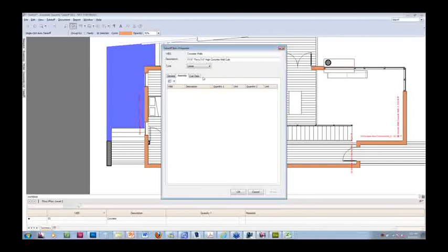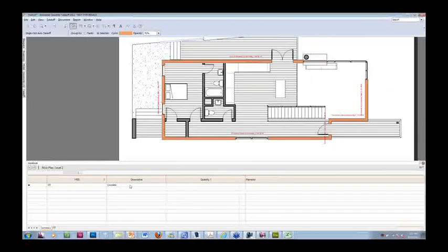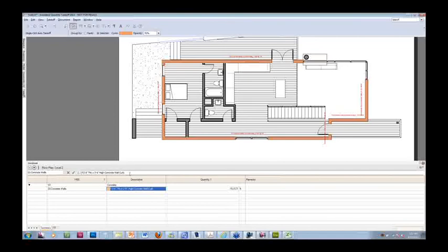And you can add what they call a formula. You can do it from here, or there's a workbook that I didn't show you, which is another way of adding information. So for the concrete category, for this wall, I can assign a formula right here. The formula is just any kind of mathematical division and simple arithmetic. So you can do divisions, multiplications, and even more complex formulas. But anyway, you can really add a lot more information to it one time,